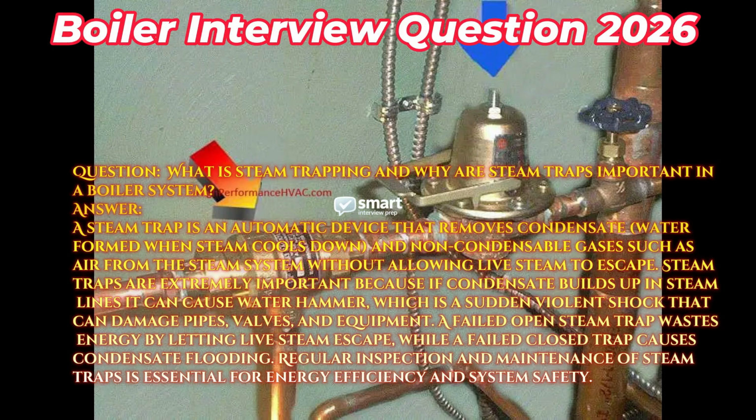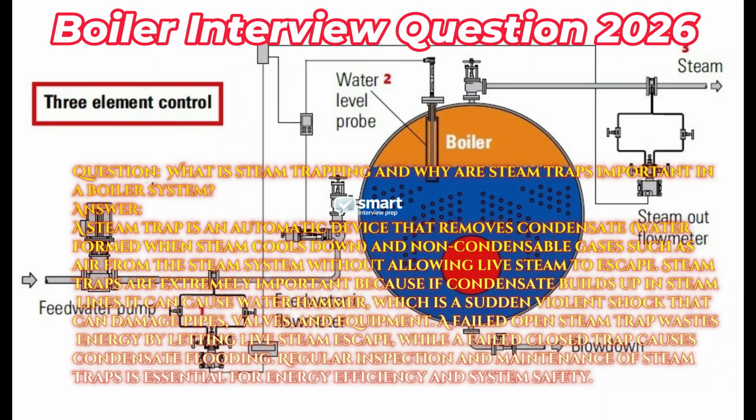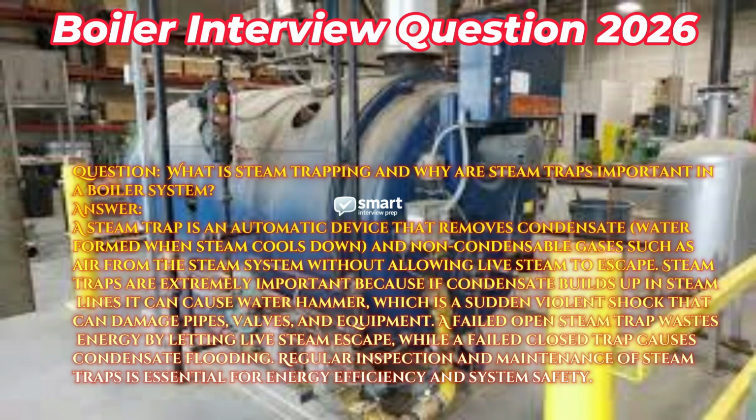Question: what is steam trapping and why are steam traps important in a boiler system? Answer: a steam trap is an automatic device that removes condensate, water formed when steam cools down, and non-condensable gases such as air from the steam system without allowing live steam to escape.